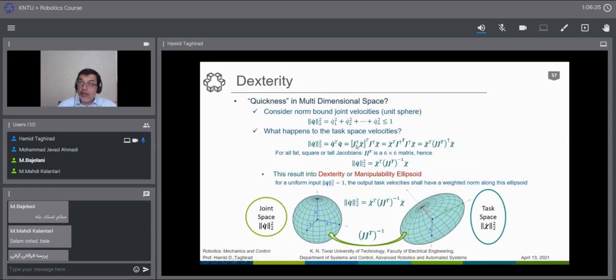If we multiply this together, this becomes the pseudo-inverse of J transpose, the pseudo-inverse of J. This is J transpose inverse. And no matter what the number of actuators is, whether it is square or not, whether your Jacobian is fat, being this way, or tall, being this way.